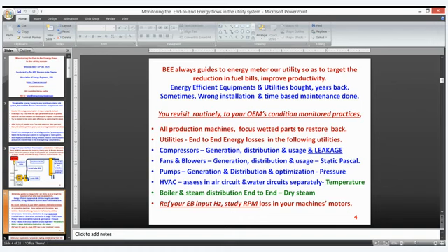For the boilers, the steam distribution end-to-end, dry steam is more important. See, many industries have considered, not only for package boilers but for the high-end boilers also, that a moisture separator is becoming mandatory, not only on the boiler outlet header, but also on the PRDS, and also on the flow metering side, wherever the dryness fraction needs to be maintained. The wetness should be less than 5%. See, 95% it needs to be dry. That is the area that we have to look into.